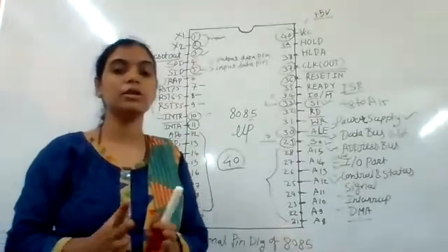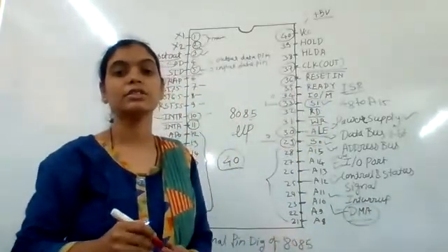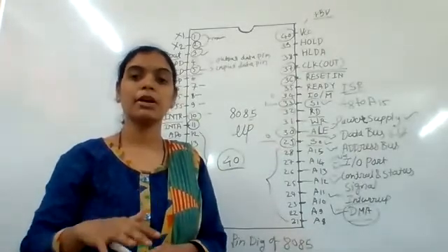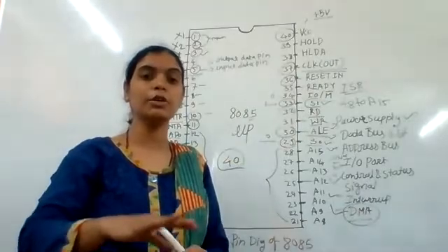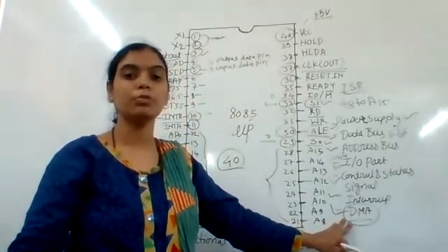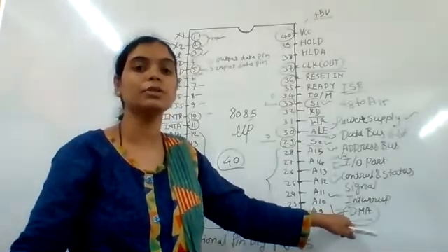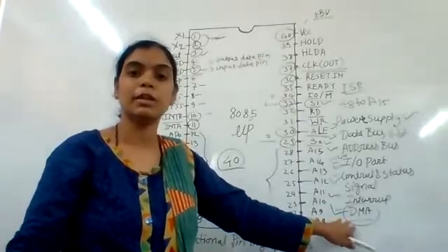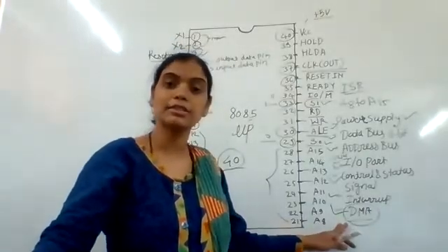Now we see about DMA, our last point. We are aware that memory and IO devices are connected with each other by the microprocessor. So the intermediator, that is the CPU, manages the data transfer between input-output devices and memory. However, when a large amount of data is to be transferred between IO device and memory, the CPU gets disabled. This transfer is managed by an external control circuit.